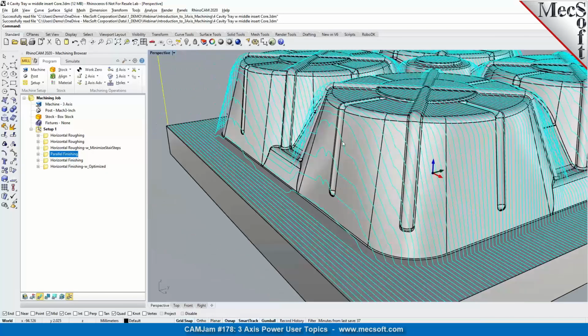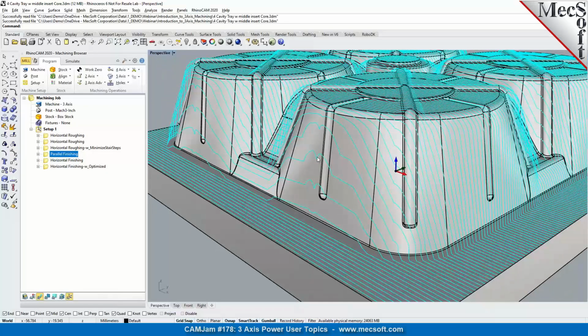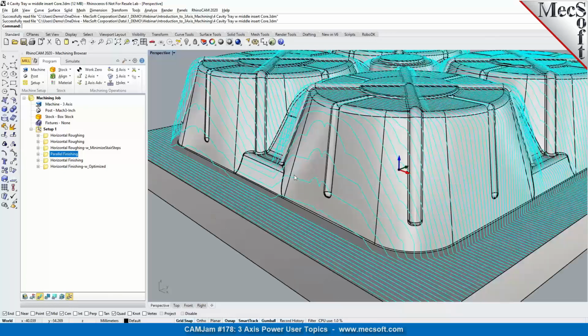So to eliminate these steep areas that you're noticing here, and the scalloping that you're noticing in the toolpath, you will need to change the angle. I just wanted to give an analogy of why we're seeing these little jerky motions when we're going along close to the edge of a vertical surface.